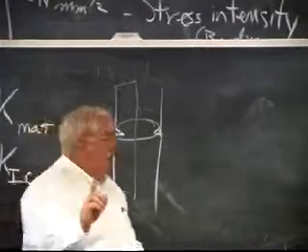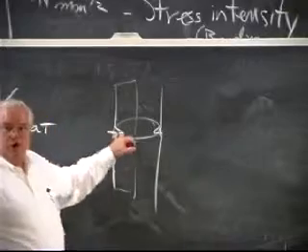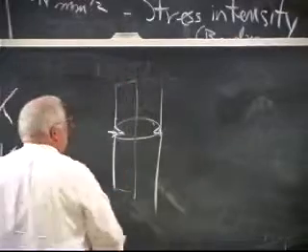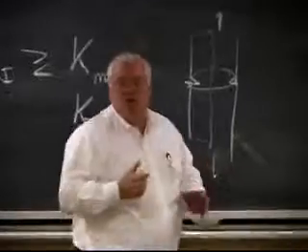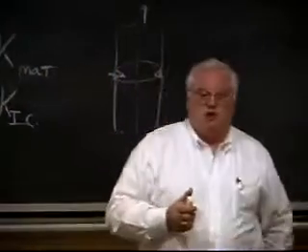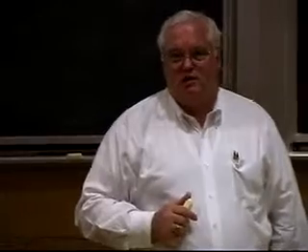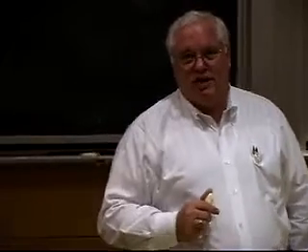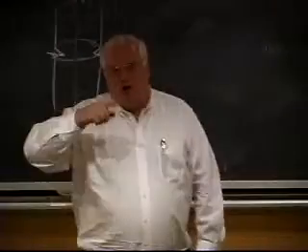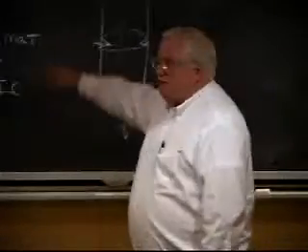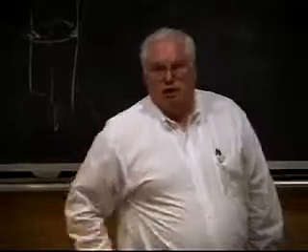Well, I take it back. That's true for tension, where I'm pulling. If I'm actually twisting, if it's in torsion, I think I may have to go back to my fracture mechanics book and look and see what the value is. Because in that case, I've got to stop to think about what it is. It's probably still that value, but the pre-exponent or the geometric factors might be 2 or 3 in that case. I have to look at it.